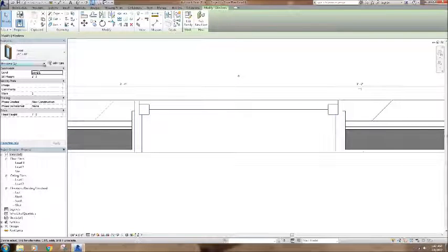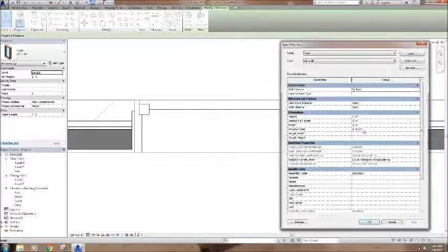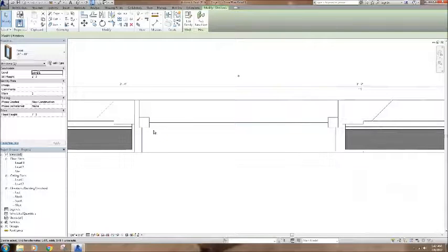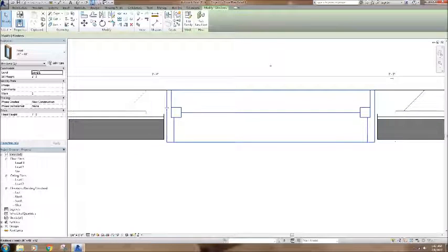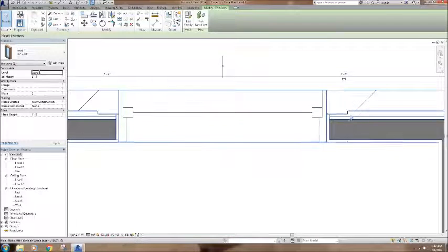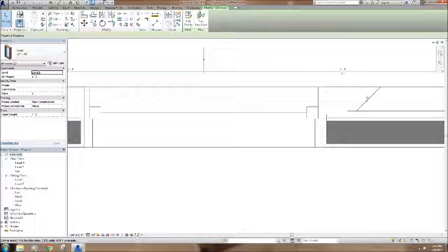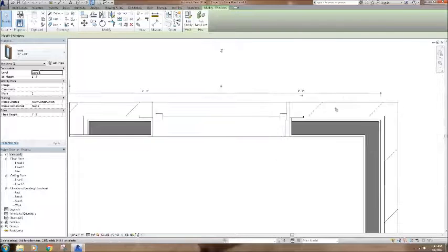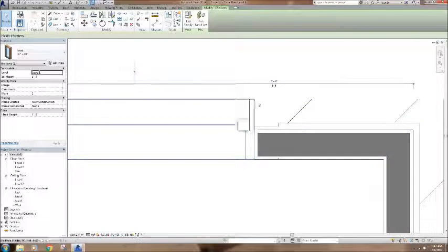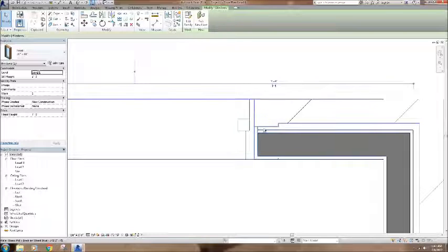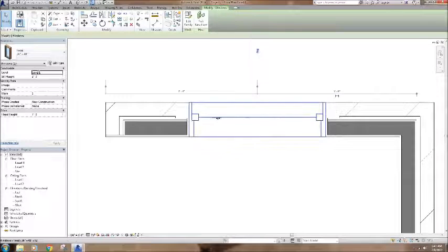Within Windows, and I'll get into this in a little bit, this is set to 3/4 of an inch. If, let's say, I make this 3 inches and hit OK, that pulls this back a little bit, and now this starts to return to a better location. And this thickens up where my exterior is, because it's basically returning the exterior cladding back to wherever my window is set.